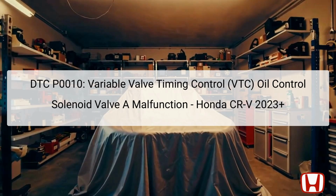When the engine control module, or powertrain control module, PCM, detects that there is a significant discrepancy between the commanded current sent to the VTC oil control solenoid valve A and the actual current being received, it triggers the DTC P0010. This could lead to various performance issues, including decreased engine efficiency and increased emissions, impacting overall vehicle functionality. Correctly diagnosing this fault is critical for restoring normal performance and ensuring compliance with environmental regulations.